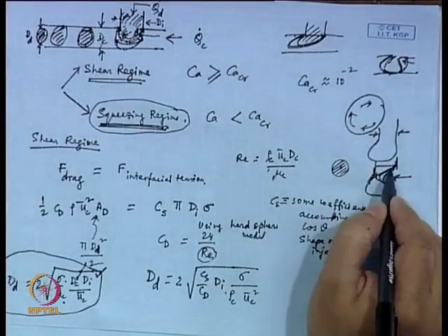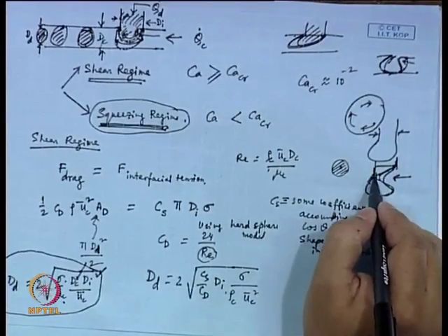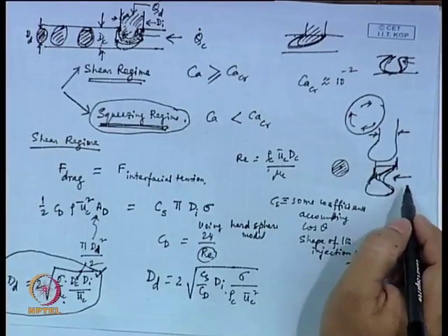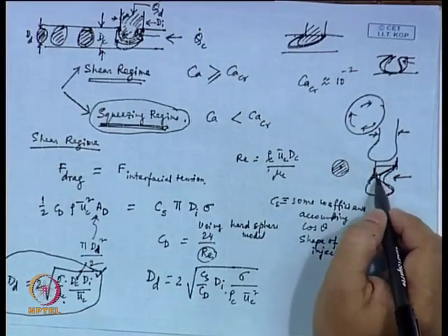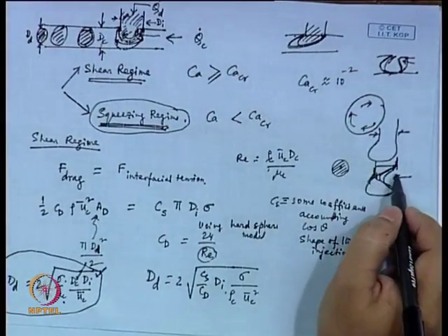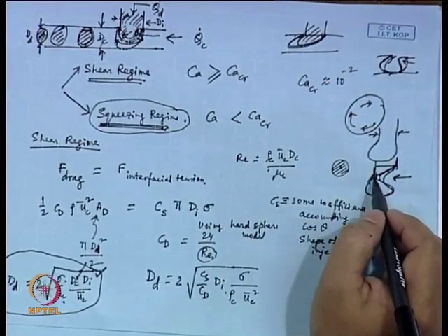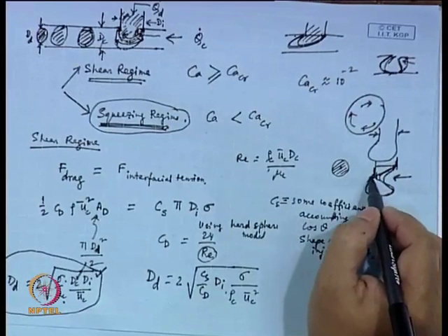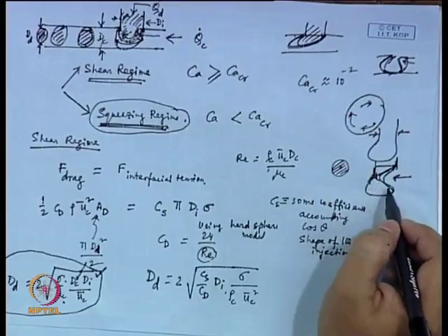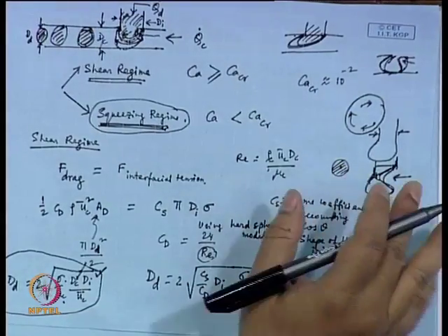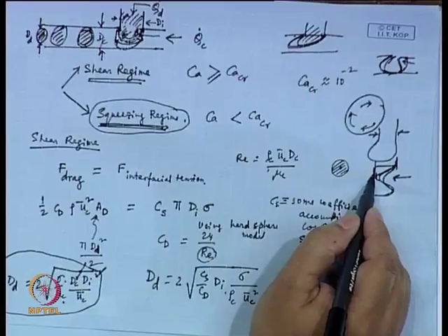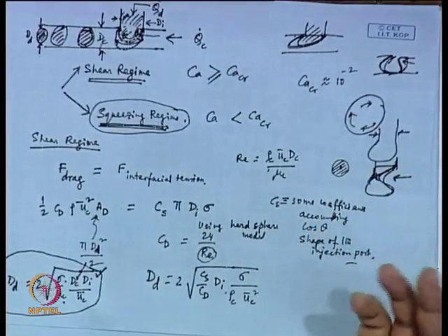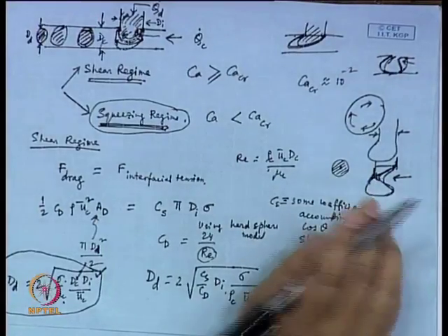If you do not want to go from geometry, you can say when this thickness gets 0, because this QC dot that you have is fixed, that is constant. So, it has to eat away, and the rest of it is geometry. Now, you can say that okay, it will reach the end. When it reaches the end, I will consider the droplet to be released, or you can say that still there is some delta left, and at that point some Rayleigh plateau instability caused this to rupture, because here it is a neck. So, at some point there is a rupture. But anyway, that delta would be very small.